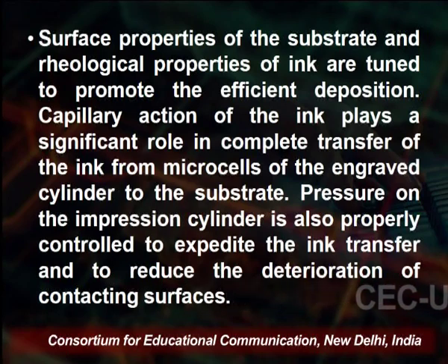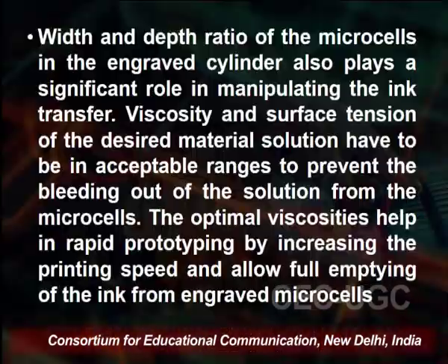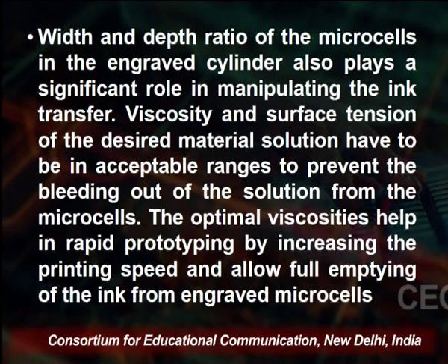and to reduce the deterioration of the contacting surface, just as the doctor blade was used. The width and depth ratio of the microcell in the engraved cylinder also plays a significant role in manipulating the ink transfer. Another important point, which we already discussed in screen printing, is the viscosity of the ink.